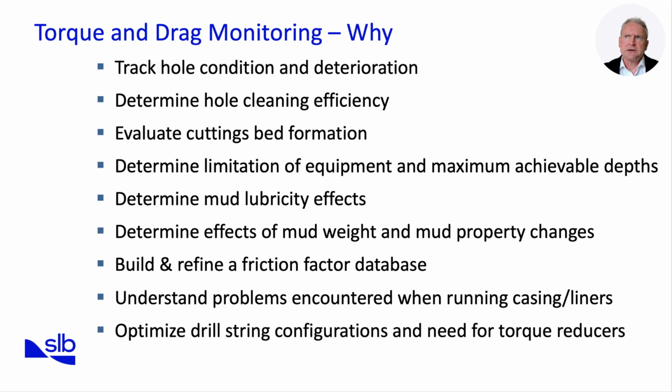Additional insights include the effects of mud lubricity, mud weight, and property changes on drag performance. By comparing data across different drilling fluids and well sections, we build a friction factor database that strengthens future well planning. Ultimately, monitoring is about prevention, detecting and understanding problems before they stop progress, whether running casing, liners, or drilling ahead.